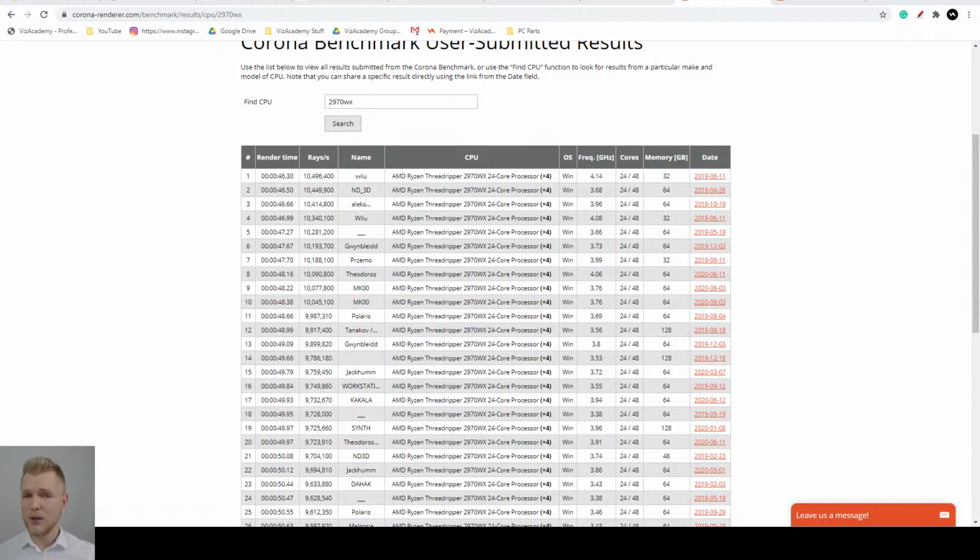But GPU rendering tends to be a little bit faster on, let's say, mid-core level. So if you're just going for medium quality, I would say GPU is for you. But if you're going for high quality renders, you probably want to go for CPU.